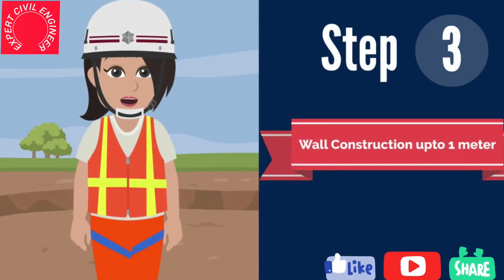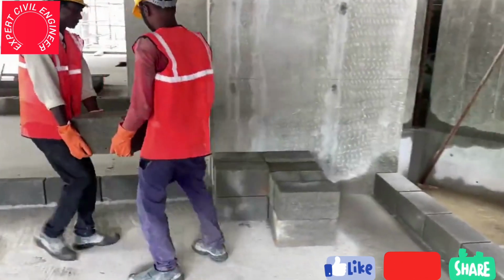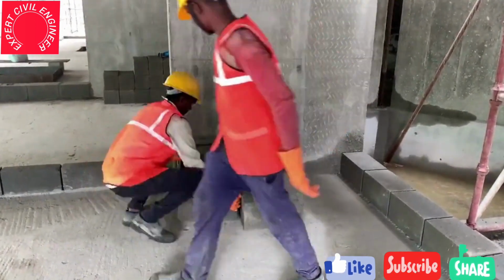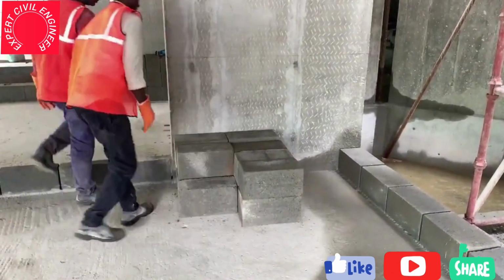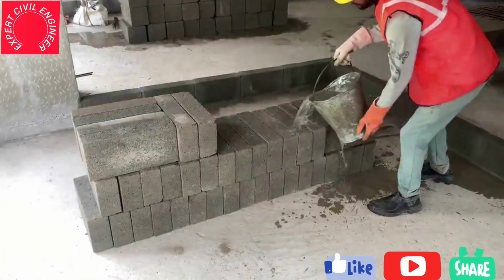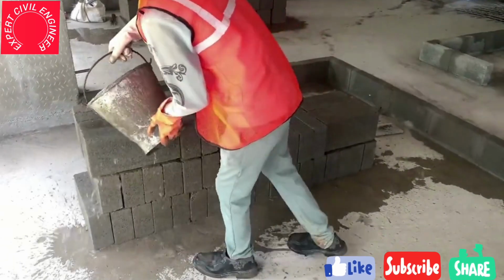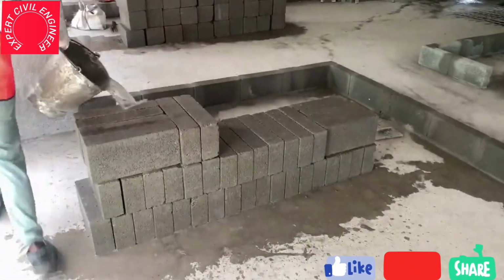Once the marking course activity is completed and cleared by the engineer in charge, further the wall construction activity will be commenced. Let us quickly check the step-by-step procedures of the next activity. The quantity of blocks needed for the blockwork must be transported or shifted to the designated location in accordance with the project requirements. For improved mortar adhesion and reduced drying shrinkage, thoroughly wet all the concrete blocks in water for 24 hours before laying them.